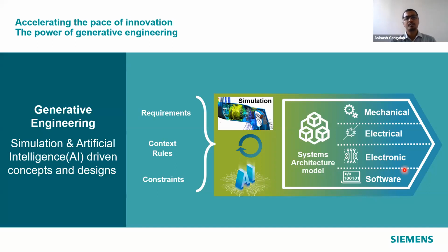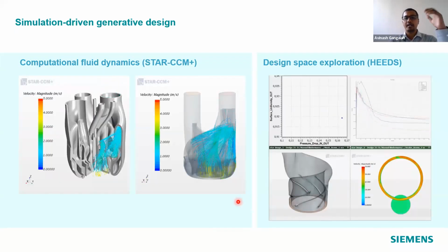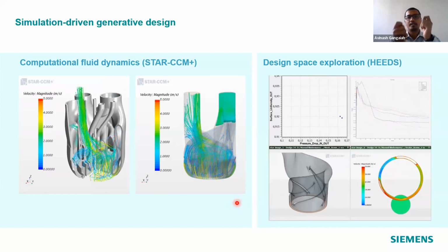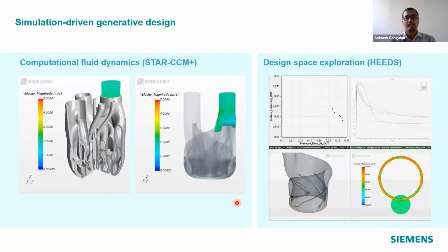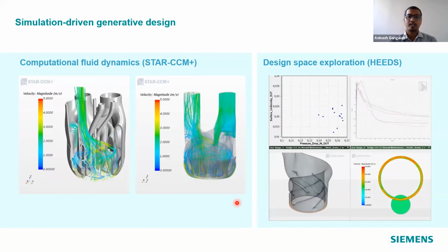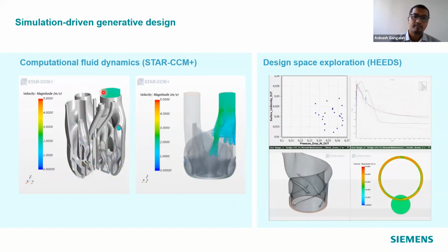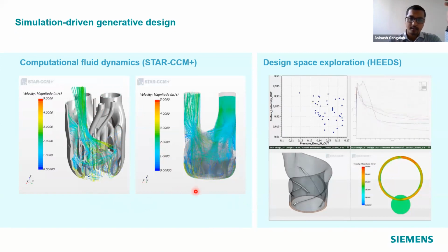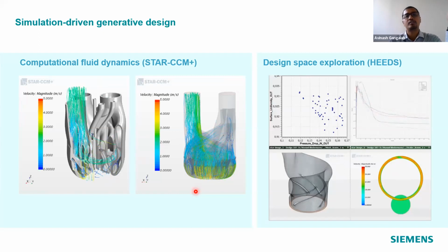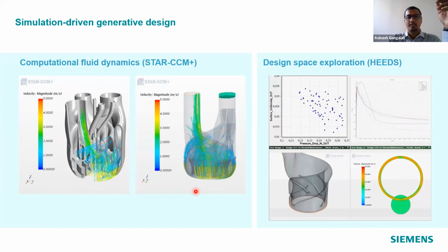So one of them is where you take a standard design and then say, okay, these are my input load conditions, these are my fit and finish, this is where that particular component will fit in, and then you let the technology take care of the calculation piece, where it will run a number of iterations to come back to you with a final iterated model, to give you design data that will meet your need in terms of, let's say, one of your goals is to reduce the mass, while the strength is not compromised and the goal is met.